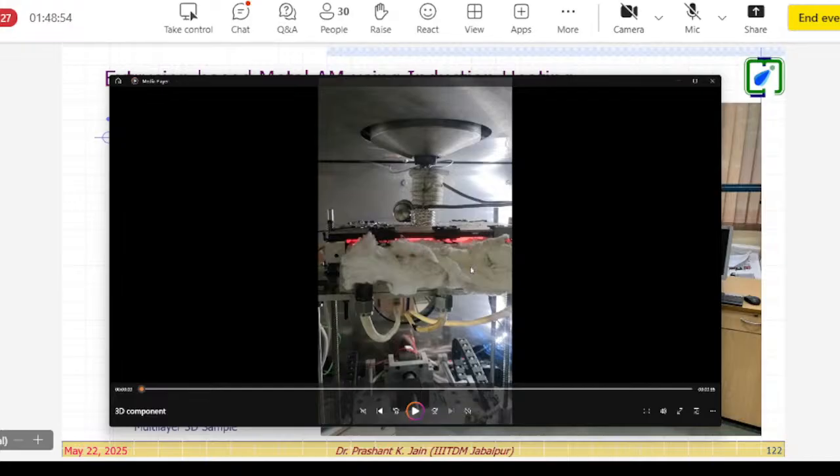See here inside also, you can see this is the substrate. Red heated is showing. This is the insulation plate and these are the water channels we have created to take away this heat. Otherwise, once 600 degrees centigrade temperature is achieved with induction heating, the entire chamber becomes very, very hot, and this can damage the lubrication system of our CNC positioning system. This can affect our ball screws and stepper motors. So that heat has to be taken away. So not only the insulation, but we have to have water flowing to carry away this heat outside the chamber.